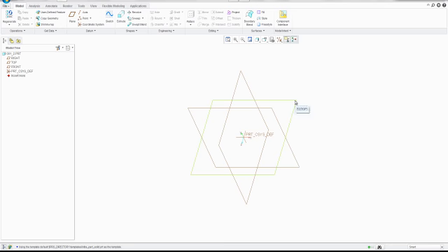So I'm going to do my sketch on the top plane. I'm going to select my top datum here and make sure it highlights in green so that you know it's selected. I can go into sketch and define my diameter using a circle, and we don't have dimensions to work with here. We can pick arbitrary dimensions, but I'm going to go ahead and use 80. I believe that's what I used in class the other day. And I'm going to select OK.